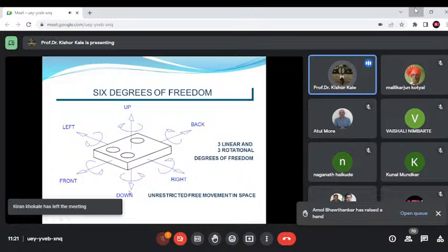Now for the secondary datum: all dimensions may not be capable of reference from the primary datum, to ensure functional relationships, accessibility and repeatability. So when you feel that the primary datum is not capable for dimensioning or verifying things, we have to define the secondary datum as well as the tertiary datum.